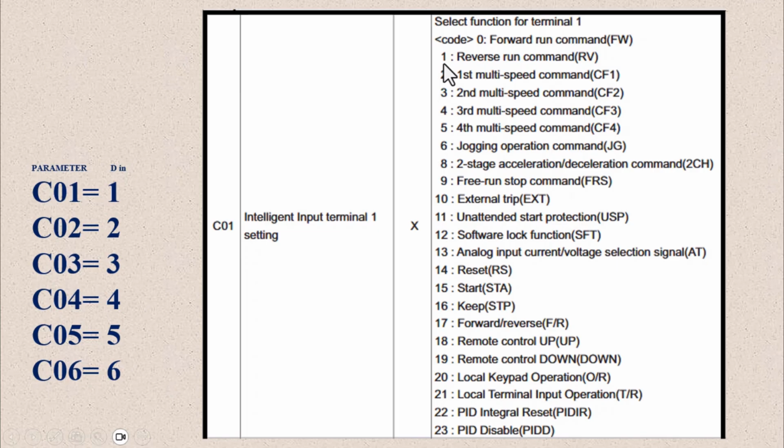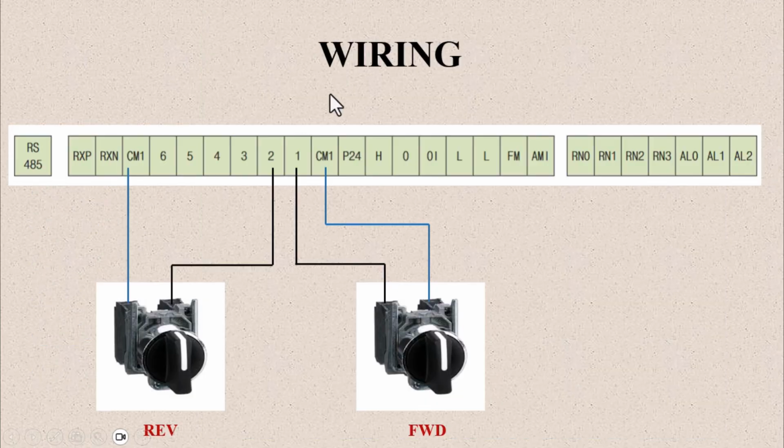So that's done. These are the specific configuration settings you need to make for the digital inputs of the E1 inverter. This is the detailed wiring example we need to follow for this tutorial. As we previously discussed, I want my first digital input to be used to assign the forward command, and then my second digital input will be used to assign the reverse command.